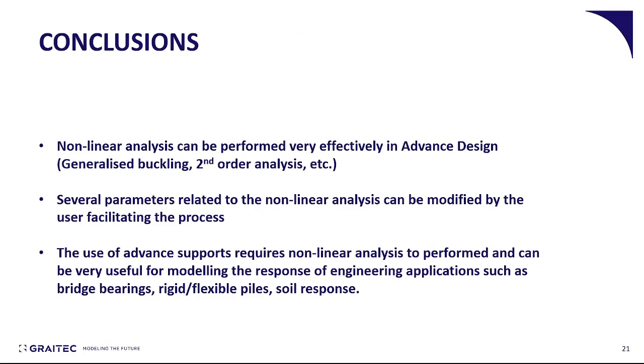Before closing this webinar, I would like to summarize the key points of this short demonstration. First of all, the nonlinear analysis can be performed very effectively within the advanced design interface. Some functionalities that can be very useful is the generalized backlink, the second order analysis in order to take into consideration any P delta effects. Several parameters related to the nonlinear analysis can be modified by the user, facilitating the entire process.